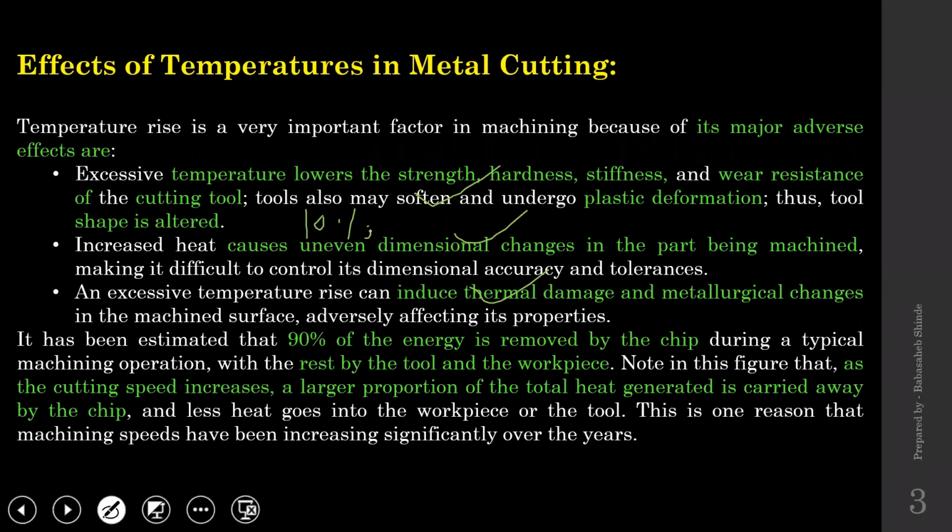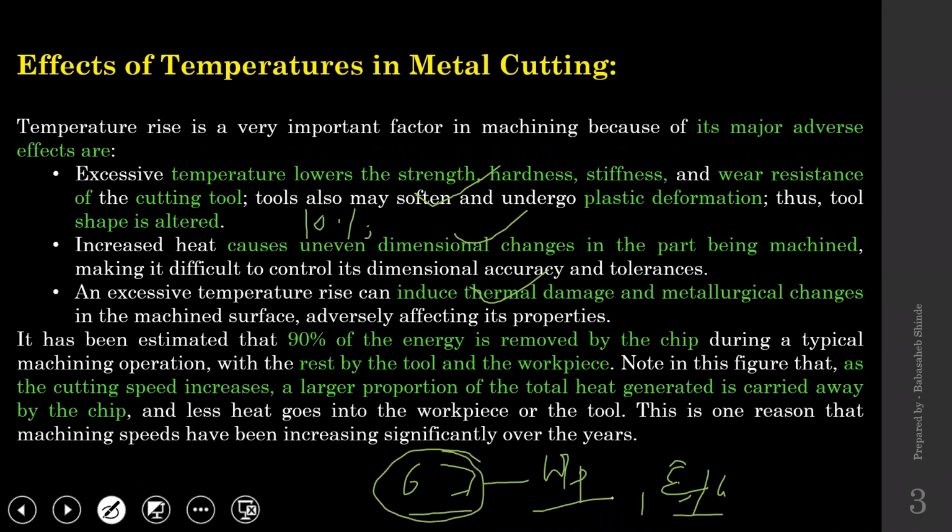Now out of that 10%, around 6 to 7% will be taken by the workpiece, and 3 to 4%, I don't remember the exact value of that one, but 6 to 7% will be absorbed by the workpiece, and 3 to 4% will be absorbed by the cutting tool.